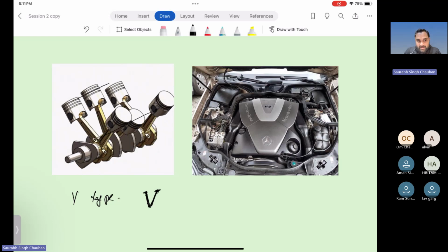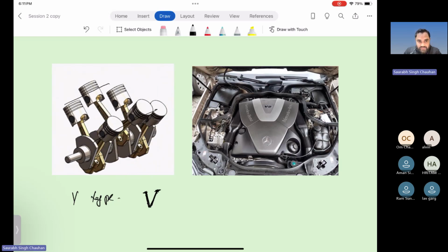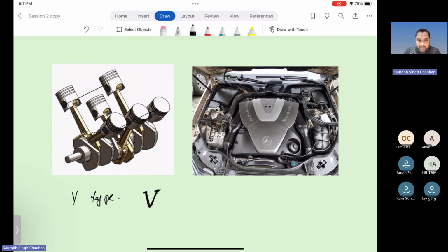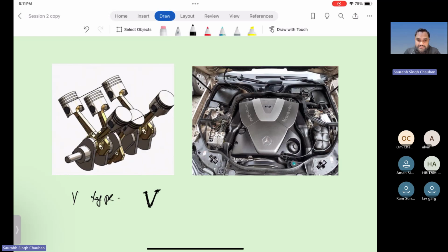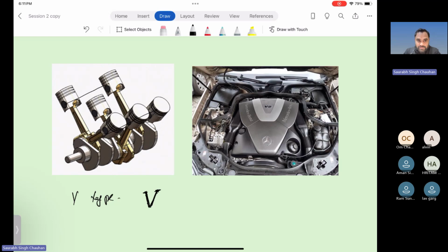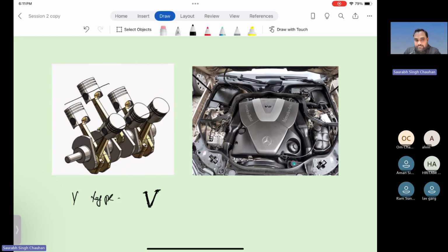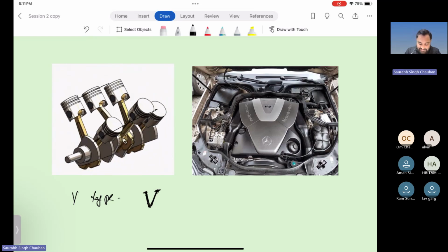So this order in which piston will go up, which piston will go down, is very intelligently designed. And the main purpose while designing these type of motion is to reduce the vibration, right? So that your center of mass should remain like that, should not move much. Otherwise there will be a lot of vibrations. So these type of special arrangements are made to reduce the vibrations and for other reasons. Okay, so here engine cylinders are arranged in V shape and number of cylinders is 6.